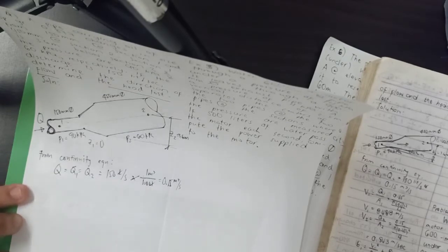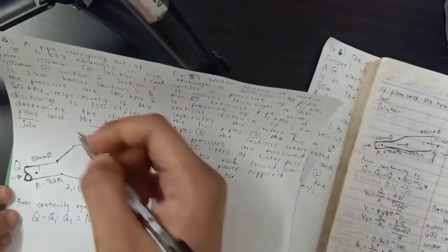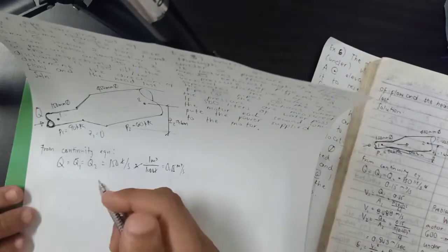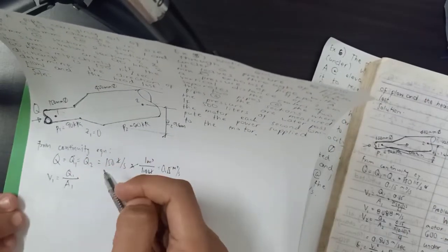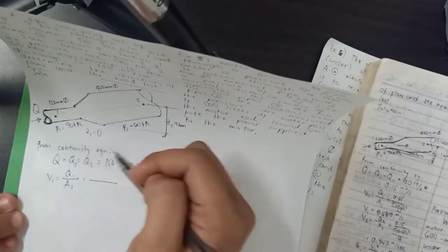So, direction of flow and head loss. To be able to solve the head loss, even though the direction of flow is clear that it's going up, let's check. So, first, V sub 1. V sub 1 equals Q1 over A sub 1. Q1 and Q sub 2 is 0.15.